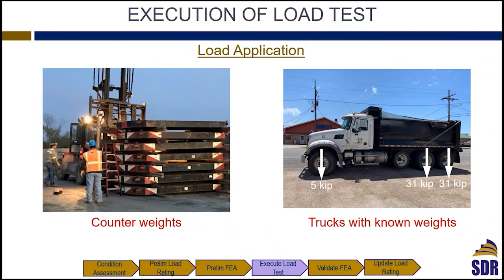Now, after that, we go to the field to load test the bridge. So how do we apply a load on the bridge, especially that this should be heavy loads. So most of the time we are using, here I'm just starting to use my laser pointer, so this helps. A lot of times we use dump trucks. So we get them filled with sand or limestone, whatever we can get, and we take those trucks to weigh stations. So we determine the axle loads, and we also determine the distance between the loads.